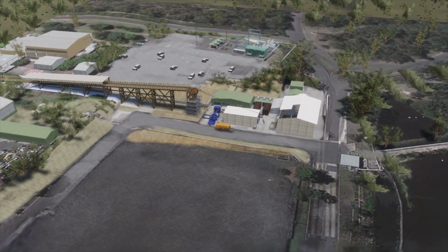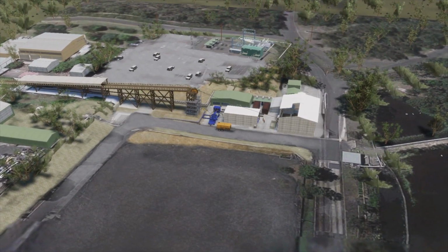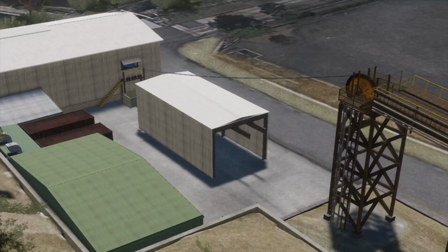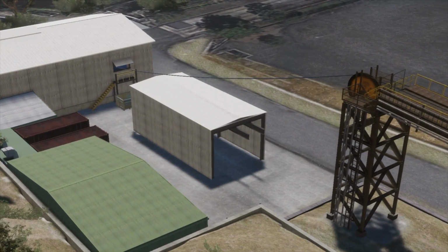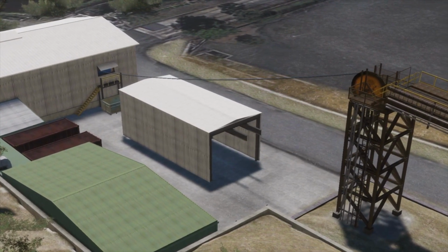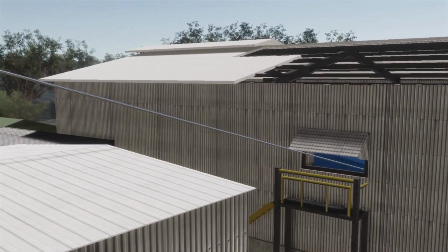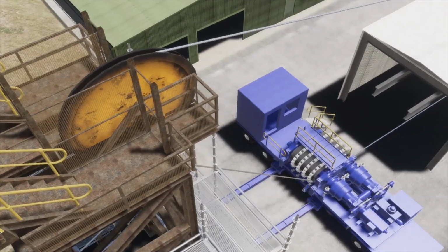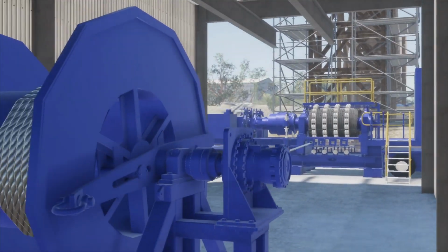In January 2020, a specialist contractor was engaged to upgrade the drift winder at a New South Wales coal mine. The contractor was required to remove the drift winder rope and developed its own procedure for the project. The winder rope was to be fed from the mine's drift winder through the existing head sheave to a mobile friction winch and then onto a rope reeler.